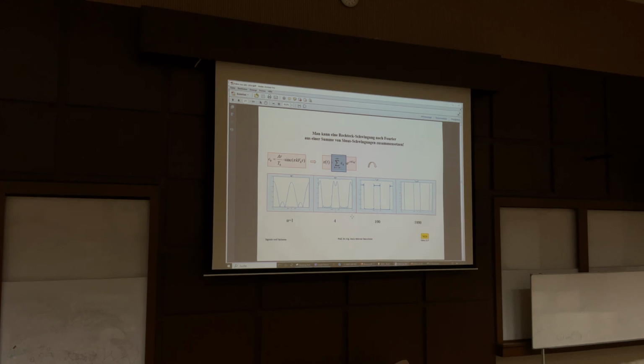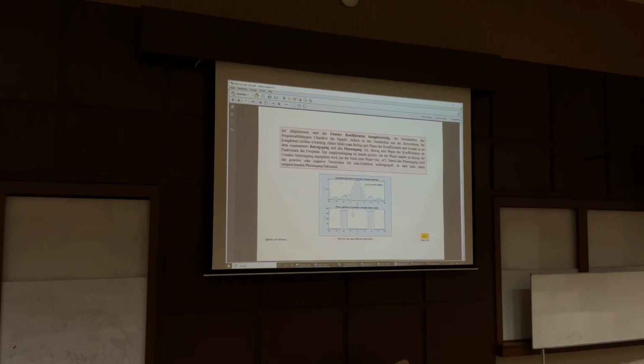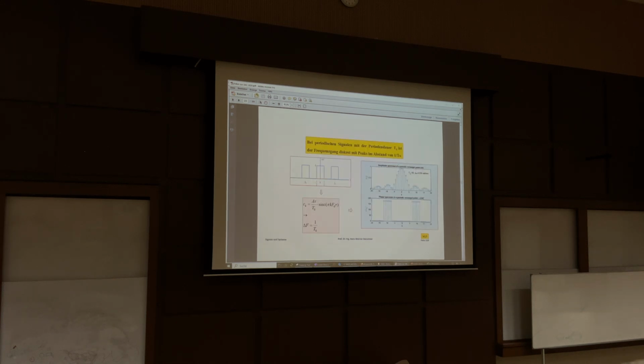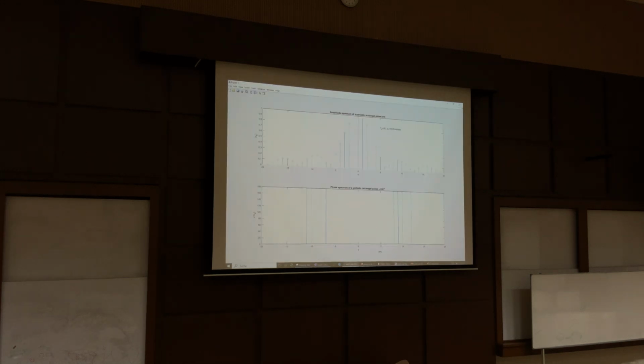And if we look at the spectrum of each of these coefficients, then we see some peculiarities. The ck is that function. k is something which changes from minus 20 to 20, for example. And what we see is that we have here single amplitudes. These are the values of my ck, the absolute values that are the amplitudes. You see here, these are the amplitudes.